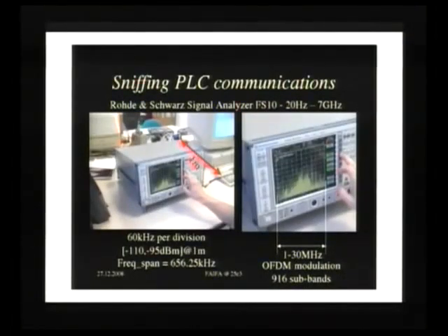So basically what OFDM is doing is splitting the binary stream between different subbands and transmitting the subbands from one part of the electrical network to the other. If you have perturbation between these bands, they will not block the whole band, because OFDM is very strong against being perturbed by only one subband.